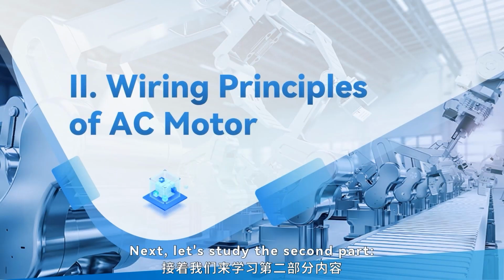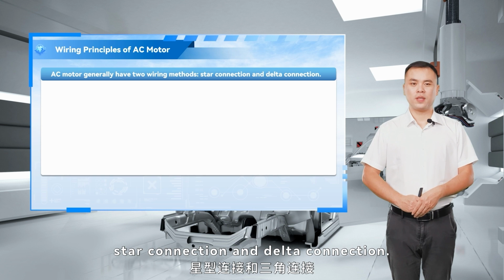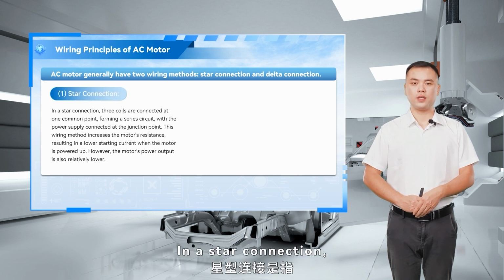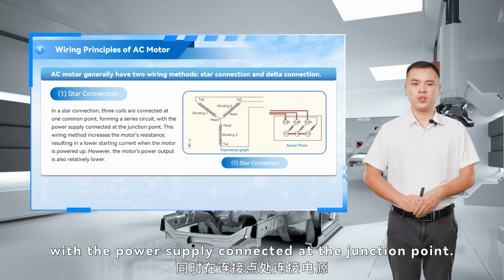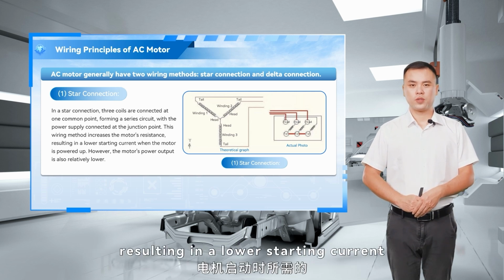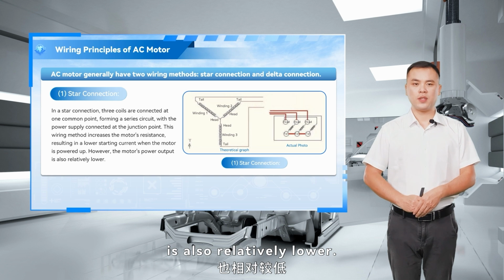Next, let's study the second part, the wiring principles of AC motor. AC motor generally have two wiring methods, star connection and delta connection. 1. Star connection. In a star connection, 3 coils are connected at one common point, forming a series circuit, with the power supply connected at the junction point. This wiring method increases the motor's resistance, resulting in a lower starting current when the motor is powered up. However, the motor's power output is also relatively lower.